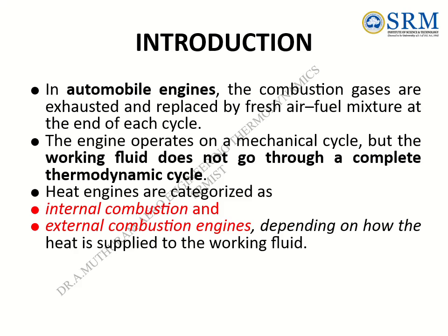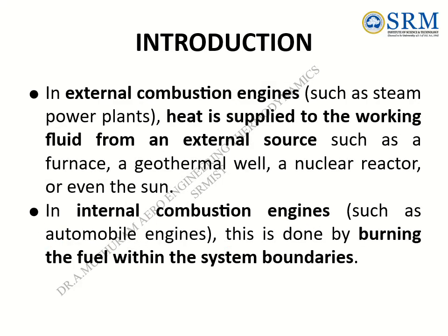Heat engines are categorized as internal combustion and external combustion engines, depending on how the heat is supplied to the working fluid. In external combustion engines, such as steam power plants, heat is supplied to the working fluid from an external source such as a furnace, a geothermal well, a nuclear reactor, or even the sun. In internal combustion engines, such as automobile engines, this is done by burning the fuel within the system boundaries.